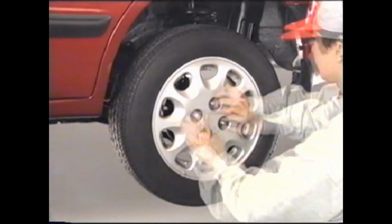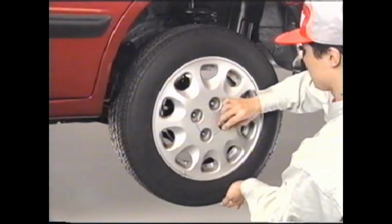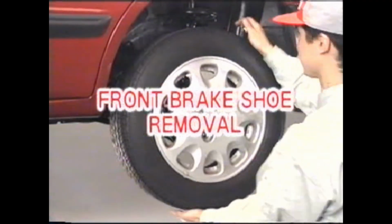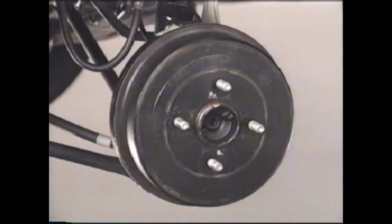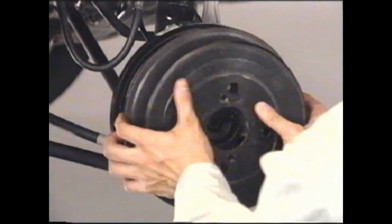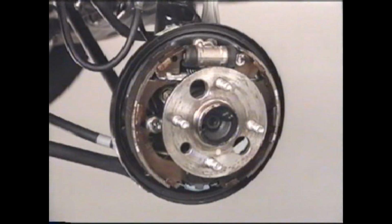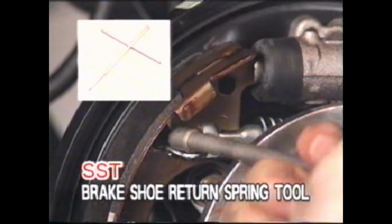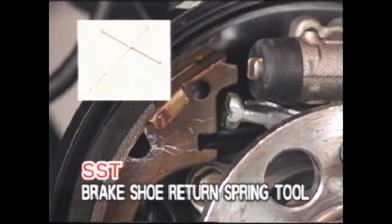Distorted brake shoes, sticking, or oil or grease on the lining could cause brake trouble. The brake shoe must be replaced if necessary. Release the parking brake. And remove the front shoe. First, disconnect the return spring using the SST.